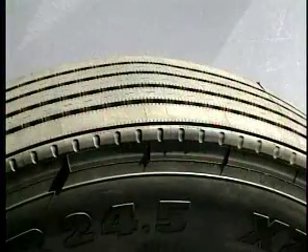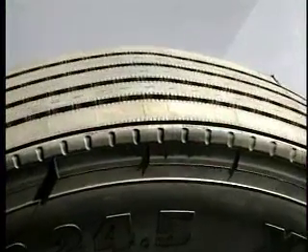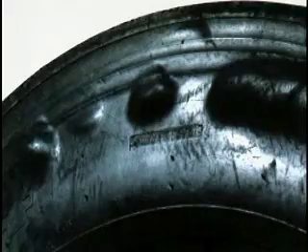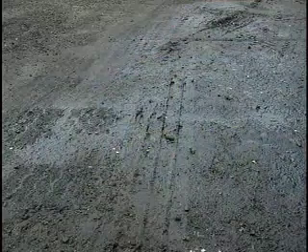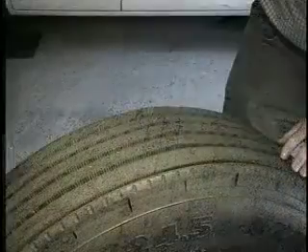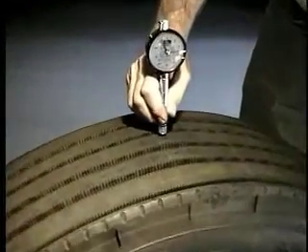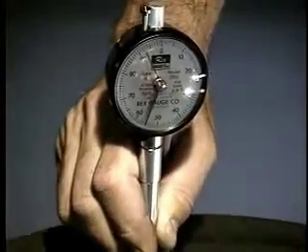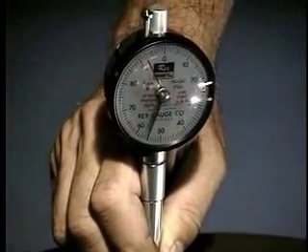This tire has what appears to be a separation in the tread area. And this tire looks like it has a series of sidewall separations. Both are the result of rubber swelling caused by exposure to petrochemical products such as grease, oil, or diesel fuel. This is evident by a decrease in the hardness of the rubber and in many cases by an odor on the rubber itself.